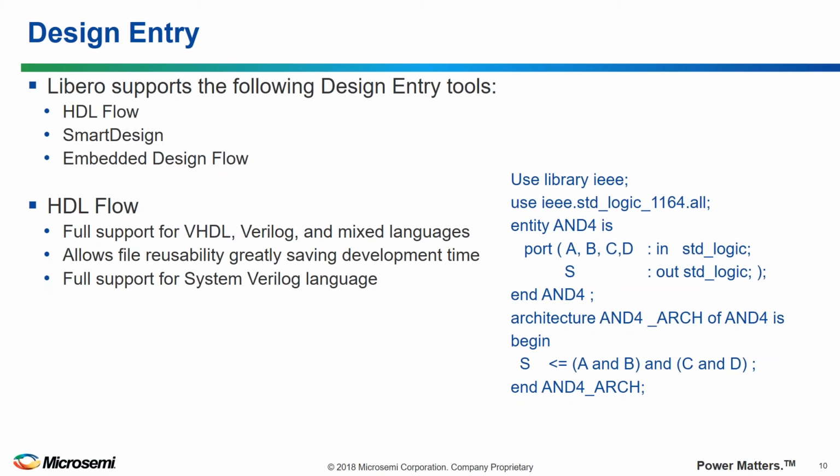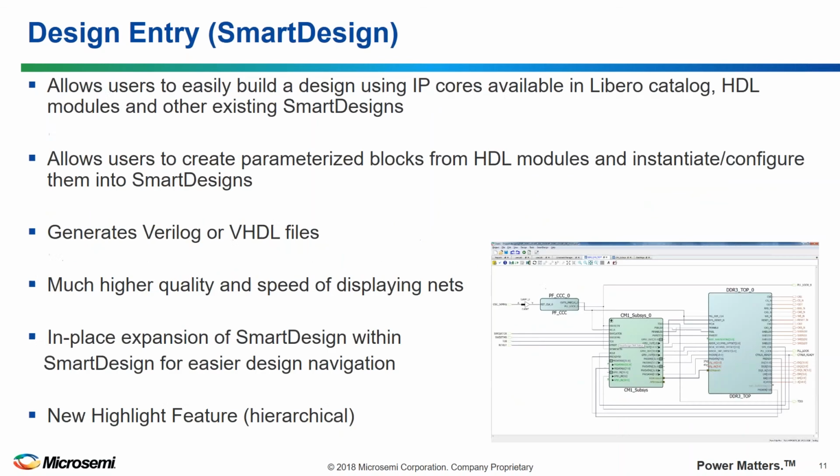For HDL, we support either VHDL 93 or VHDL 2008. We support Verilog 2001, and we also support SystemVerilog. And the entire Libero design flow supports mixed languages. So you can have VHDL and Verilog blocks in your design. You can bring them into your project. You can simulate them and synthesize them and so on.